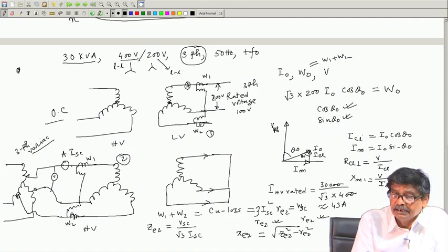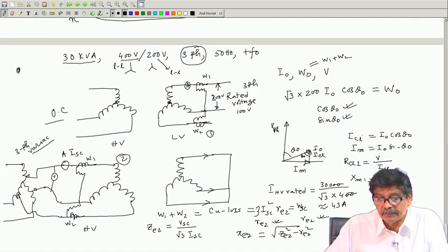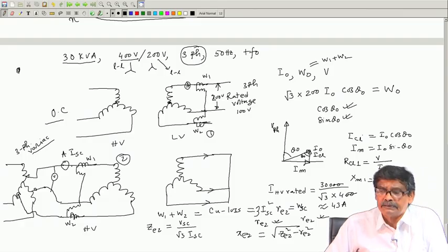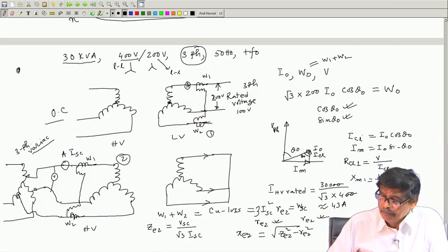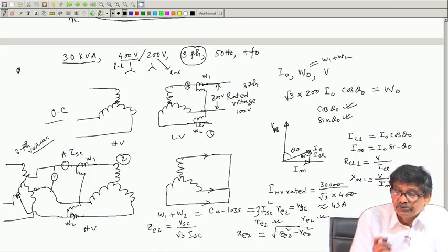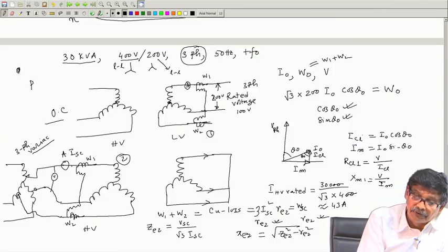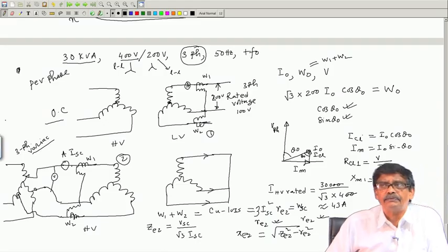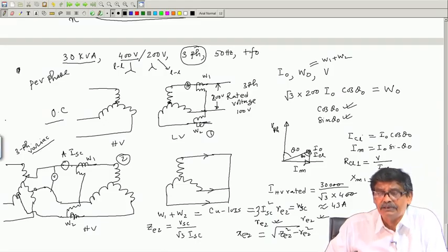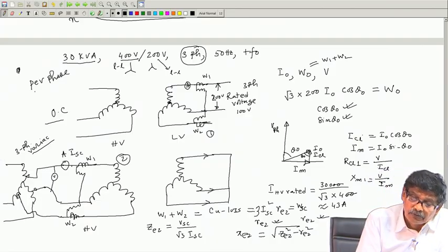What is the turns ratio here? Turns ratio of the winding, if the connections are the same, star to star or delta to delta, will be the line to line voltage ratio. So, that is the thing. Now, the question is what happens? The per phase equivalent circuit you have to draw per phase. See, I have included some worked out problems from books as well as in my notes, you go through that. Per phase equivalent circuit we refer to.